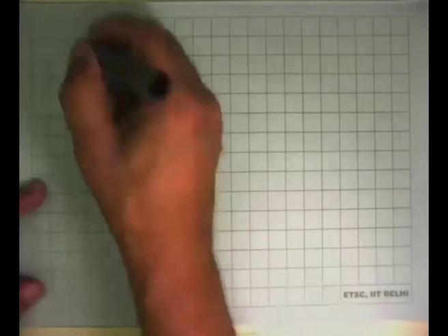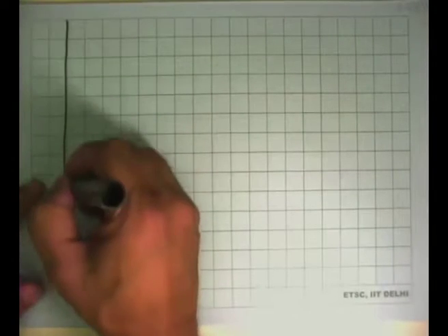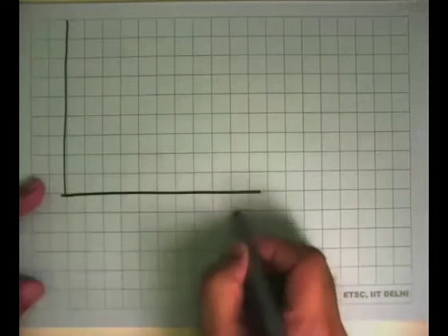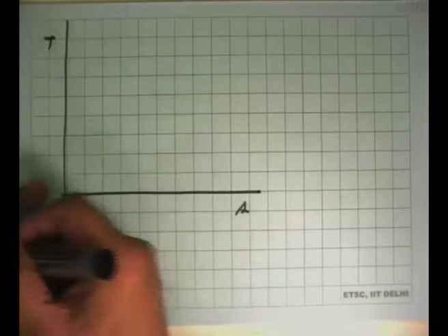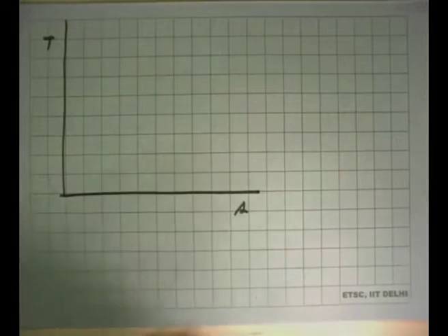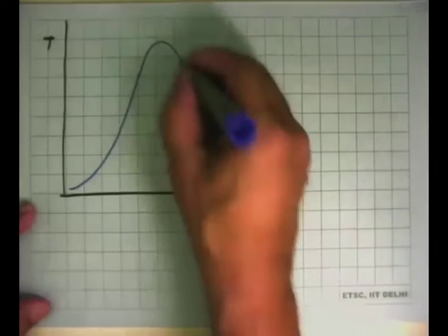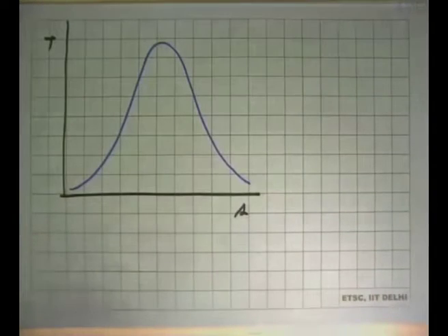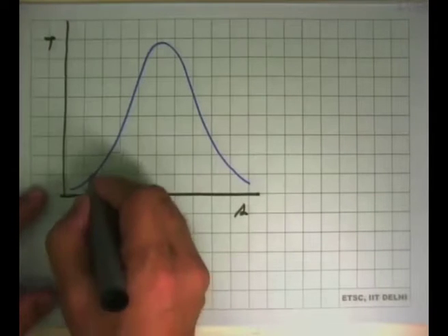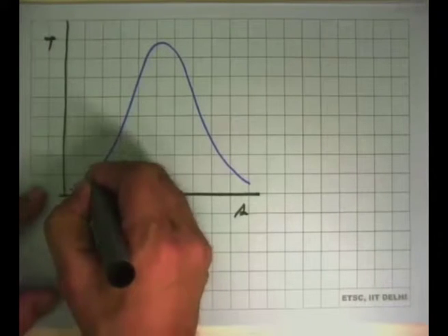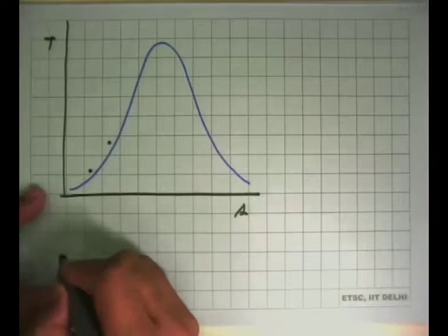Okay, there are two examples of mixing that I have given. The one thing that we will look at is what happens on the property diagrams. And I will draw the case of, say, the deaerator. That's the saturation dome. And what we have is compressed liquid coming from here, heated up to this point.